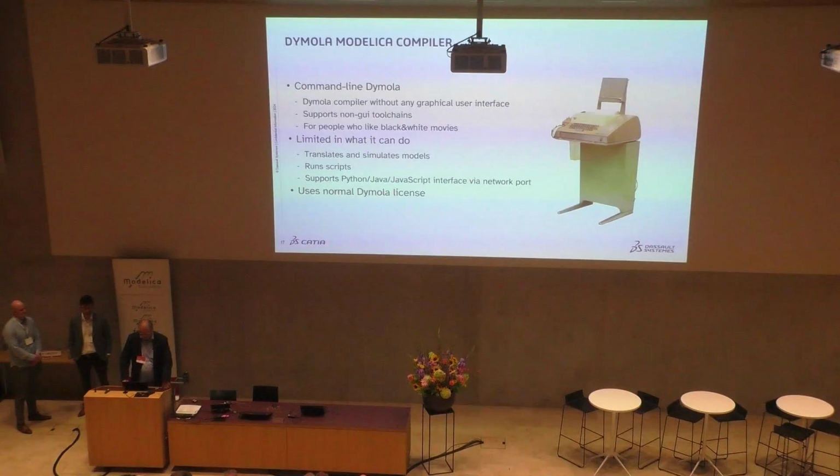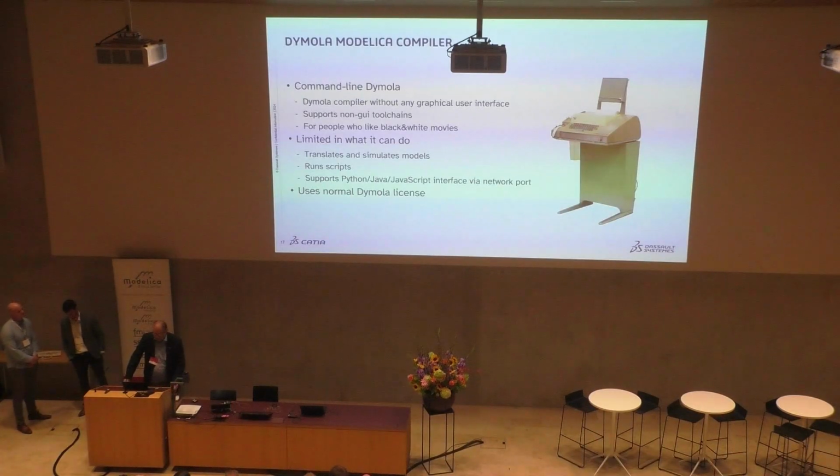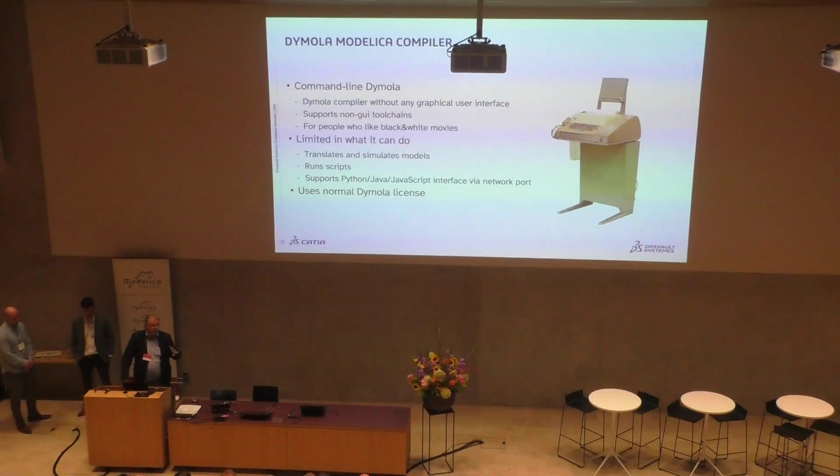Okay, it has some limitations, but it can translate and simulate models, run scripts, and it supports the Python, Java, and JavaScript interface if you want to do Excel simulation. So, except for nostalgia, the idea is that you are now able to easily use Dymola in your own tool chain. You don't have to bother about the user interface. All the error messages are sent to standard error output, so it's easy to integrate. And in an X environment, you don't even have to have X installed on your server. You can run DMC otherwise.